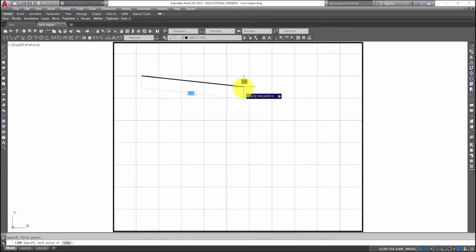Let's say I click and then I want to stop the line. To stop the line, you either hit escape, spacebar, or enter, or even right click your mouse. I hit enter, and it stops. Now with dynamic input on, I can click on the line, and these blue squares are called grips. If I hang out over one, it tells me information about the line. So I've got a line that's 4.528, at 6 degrees.